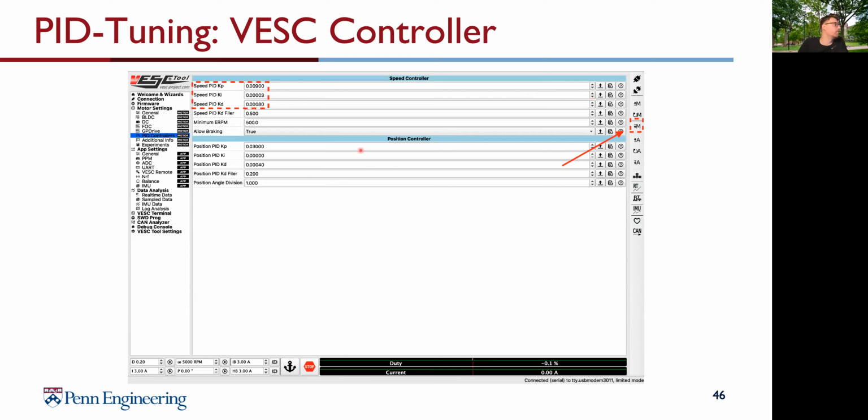And then you can inspect the system, and you can adjust accordingly by navigating to the PID controllers under the motor here. You see here your KP, your KI, and your KD parameters. You can change them and apply them to the motor again. And with the rules of tuning I told you before, like either it's an optimization or you just use the heuristic, you can gain them and apply them. And if you're seeing a lot of oscillations, try changing the speed of the KD filter, which is coming in addition here. But now you can play a little bit with the system and gain the insights.